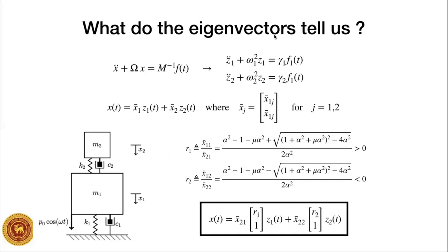We had our original system described by this coupled set of differential equations where the force was only acting on one of the masses. So the force was not acting on this one. But we found a new coordinate system using the eigenvectors of the omega matrix. And in this new coordinate system, this set of coupled differential equations becomes a set of uncoupled second order differential equations, or a set of uncoupled oscillators. But the force will be appearing in all of the oscillators.